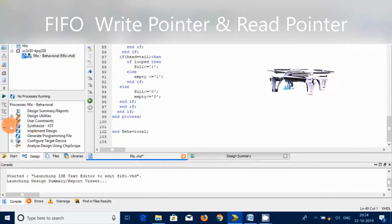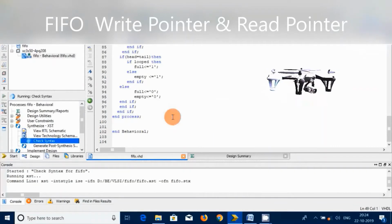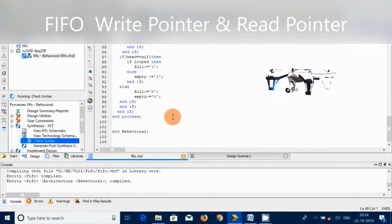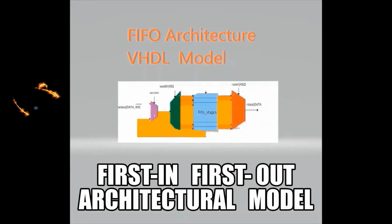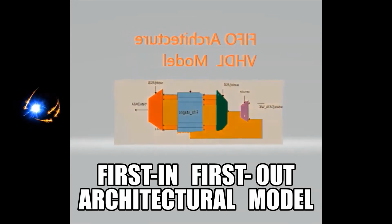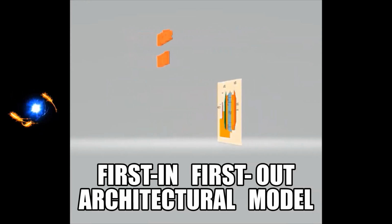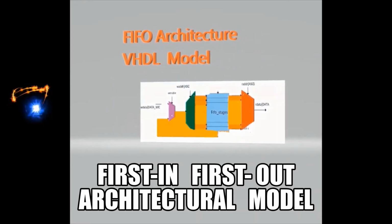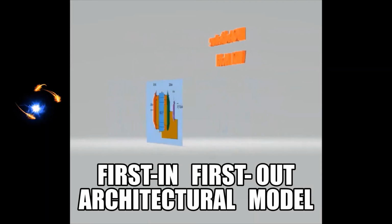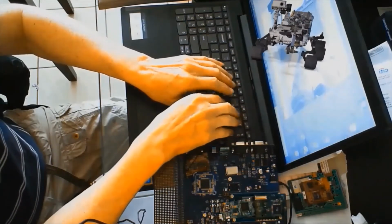In the dual port RAM model segment of the FIFO, the write counter addresses the write side of the RAM. The read counter addresses the read side of the RAM, and the control logic aims to update the write counter at each write of data into RAM, and the read counter every time data is read from RAM.